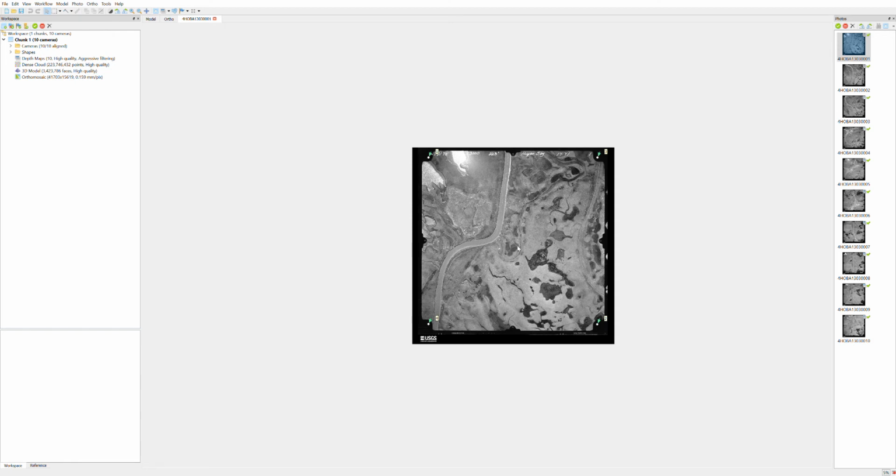And you also notice that the values that I've added here are half of the distance, so half of the width of the image itself, which was 229. So I enter in minus 114.5 millimeters for x and y. 2 is the opposite corner, and so it'll have the opposite signs but the same distance, so positive 114.5. 3 is in the negative x direction but positive y, and 4 is in positive x and negative y.